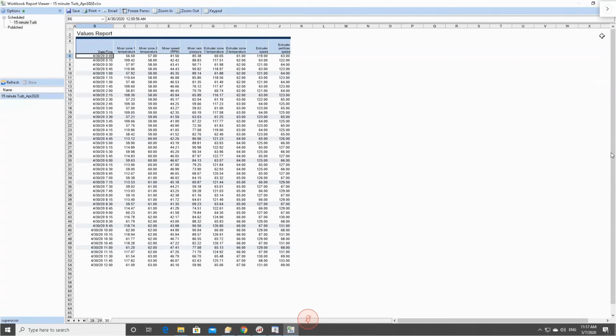And just to follow up on that, the question was, is it possible to use on-demand and scheduled report templates at the same time? The answer to that is yes. You can. In that case, you would probably configure a scheduled version, as I did, that has defined tags and defined time periods for the schedule. But then you could configure a version of that template that would open it up. For example, if you wanted the user to be able to select tags when they run the on-demand version, you could do that. If you wanted to be able to select the time period in the on-demand version, you could do that. So yes, you can combine the same data into on-demand and scheduled reports and access them at the same time.